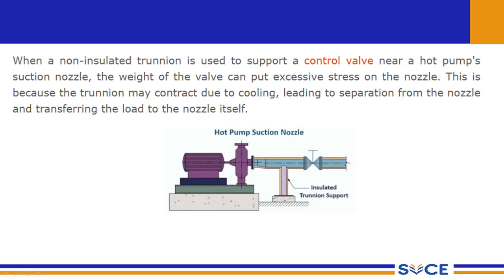If you see this picture, the drive assembly and the heavy machinery which will cause a lot of vibration are placed on a platform, and that platform is again placed on a civil structure with a strong foundation. All the vibratory loads will be taken care of by this plate and the civil structure, and the subsequent vibrations which may arise in this nozzle will be transported in the suction line of this pump.